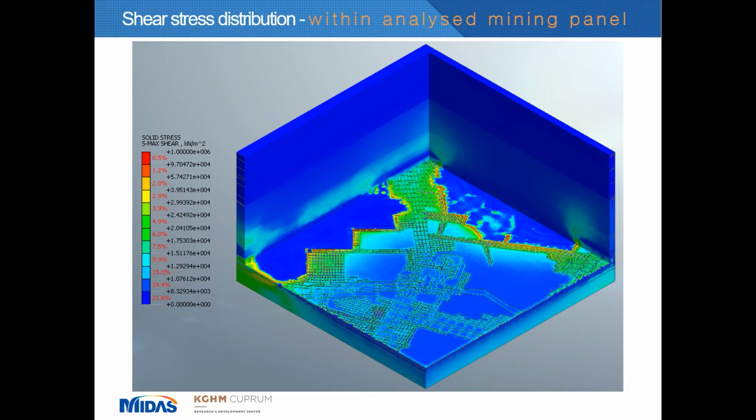And now I would like to briefly discuss the results of our analysis. The first thing which I would like to show is the distribution of the shear stresses. Shear stresses are an element that until recently was ignored because we most often focus on the axial stresses within the area of excavation, the value of which largely determines the effectiveness of the excavation support. So we analyze the axial stresses to determine what stresses we can observe in the surrounding of the workings and what support we should use to provide the stability of the workings.